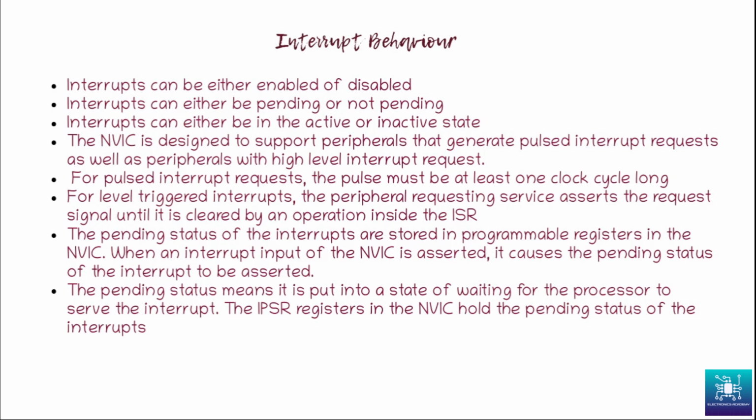For level triggered interrupts, the peripheral requesting service asserts the request signal until it is cleared by the operation inside the ISR. We will not see level triggered interrupts much, so we will only be talking about edge triggered interrupts. But had there been a level triggered interrupt, the level would have to be cleared by the software inside the ISR. So that's the programmer's job to clear the trigger.